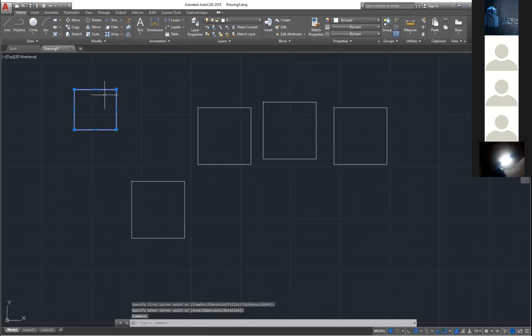You're seeing that if I want to select this, it's highlighting everything. But what if I wanted to work just with this line, okay? What you have to do is you select and explode this, and then now you see you can select the individual line. So that's the function of explode.